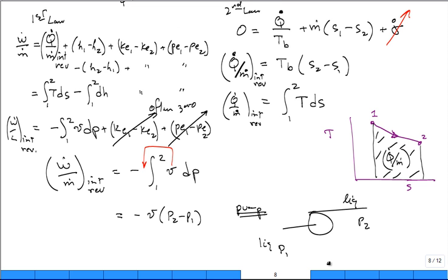The pressure goes up. So if I check the specific volume of the fluid coming in, V1, and compare it to the specific volume of the fluid going out, V2, they would be essentially the same if it's a liquid. And we have a lot of liquid pumps in practice. So the specific volume of the liquid stays the same, but the pressure goes up. So this tells me the minimum work per unit mass that is required to boost the pressure of that fluid. Does that make sense?